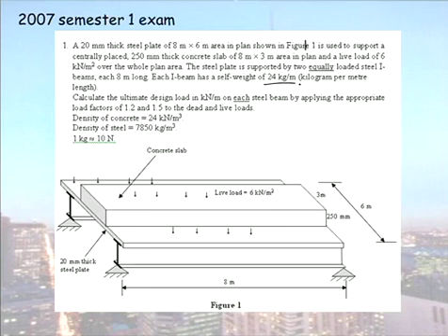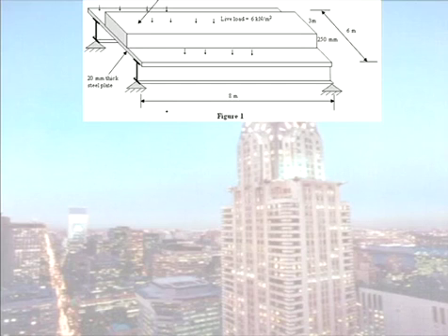So be clear what ultimate limit state load you're being asked for, whether it's ultimate or serviceability, whether it's the strength one or the deflection one. So we're given the density of concrete and the density of steel. And as I said way back in lecture 1, you can come to me and say units of density, Lizzie, are not kilonewton per metre cubed. No, we're engineers here. We're lazy when we come to our terminology. Look at the units and be clear what units your values are in. Okay, so for a question like this, I'll then just move across. We'll look at calculating the dead load first.